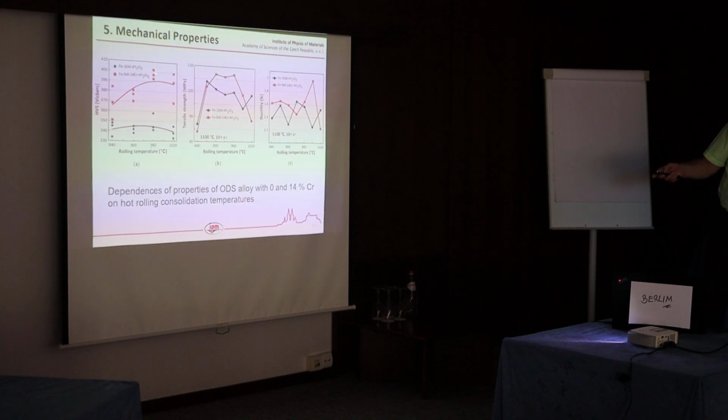So you can see we get some maximum at about 960 degrees, but for the ultimate strength, there is quite a large window between, let's say, 850 degrees and 900 or 1000 degrees basically. So which is convenient, it doesn't dramatically depend on the rolling temperature. So this is the ductility. You see it's very low values, about 1.5%, sometimes 2%.